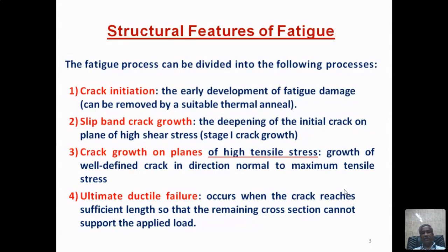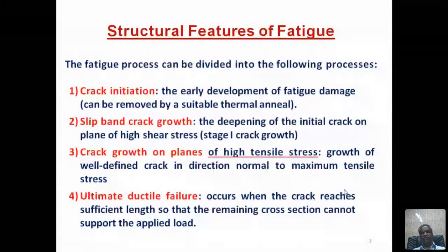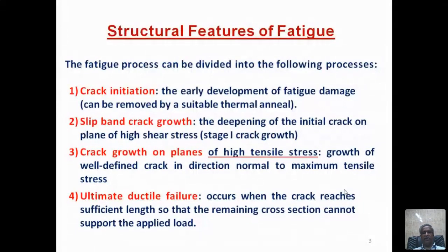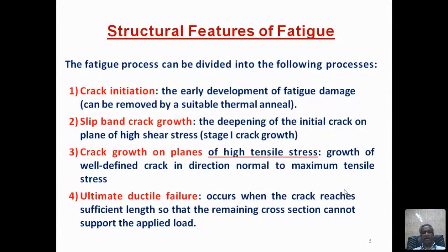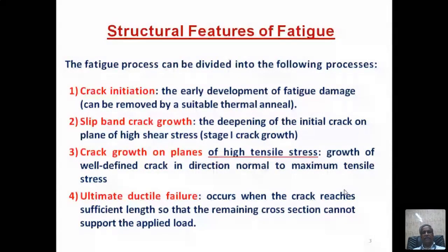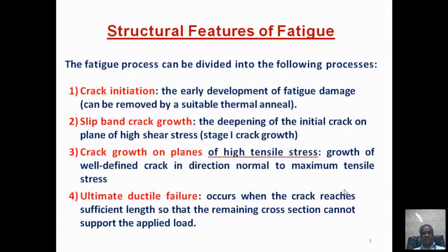If you are able to detect this petty crack at the initial stage, then you can remove it, or you can avoid further growth of that crack initiation. It can be removed by a suitable thermal annealing process, some suitable heat treatment process. You can remove those cracks.